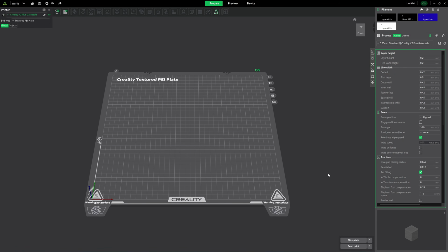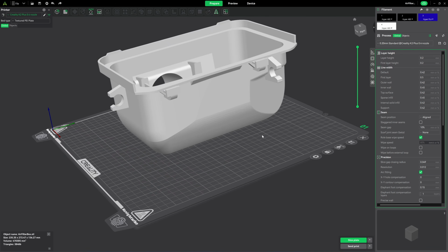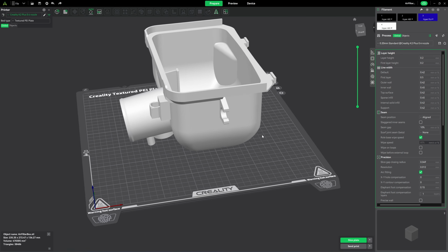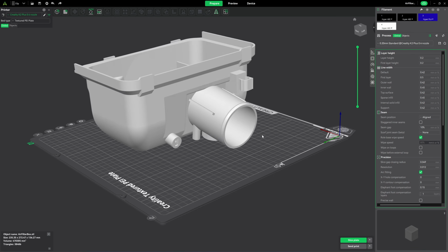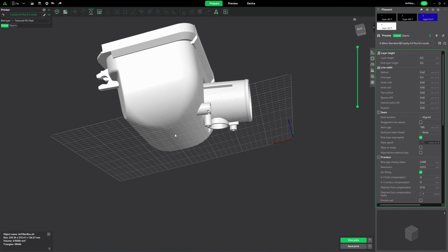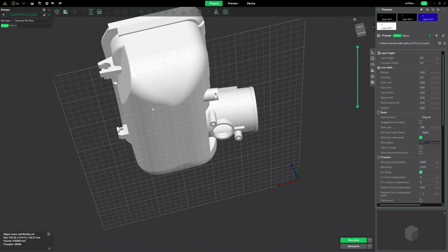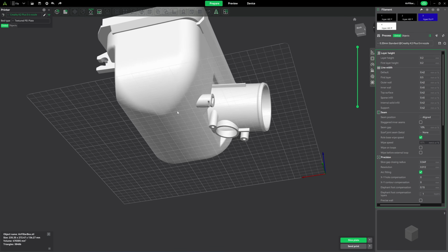Okay, so here comes the most difficult part of this project, 3D printing. I'm going to print this with ABS, and the first thing you have to consider is the orientation of the object. If I put it on the flat face like this, the curved part will need a lot of support and it's on the outside. And I probably need to do a lot of sanding and the surface quality won't be that good.